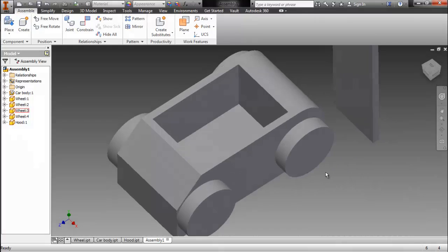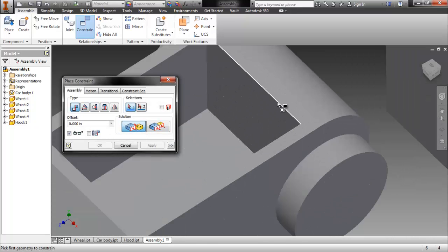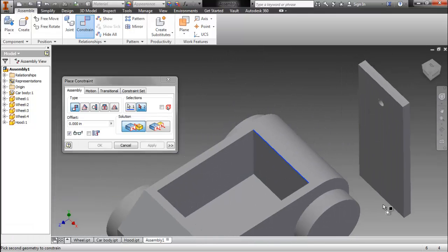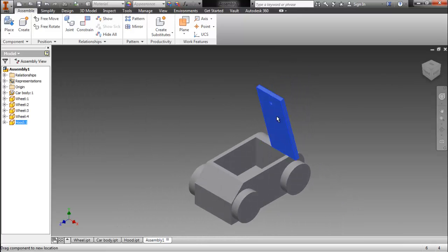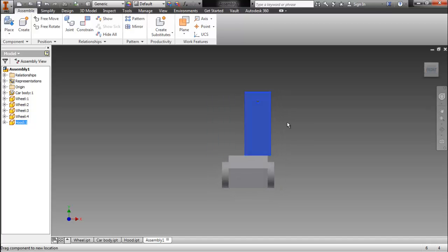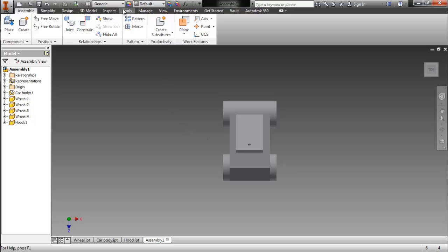You can constrain faces and axles, and you can also constrain edges. So from here, I'm going to constrain, click on this edge right here, and as you can see, it turns to a white color, and I'm going to click on this edge right here. From there, you can see that this can only move when it's contacting that hinge, or those two contact points. But there's also left and right play. In order to fix that, you can mate two faces on the inside of the vehicle. But if you look at the top right here, and then you bring those lines back up,